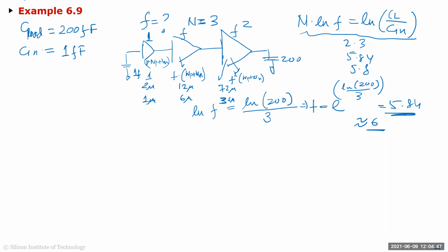So you can see that if I just took a 72 by 36, it's not going to work because this tiny guy will have a huge delay. So you actually taper it down. So you take 12 by 6 and then you do that, right? Everyone got this, right?